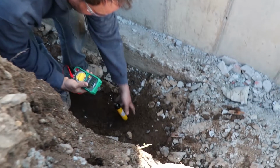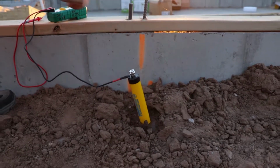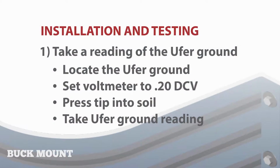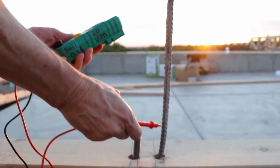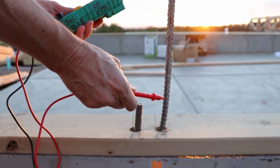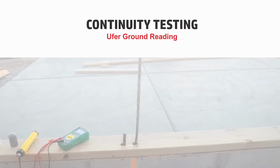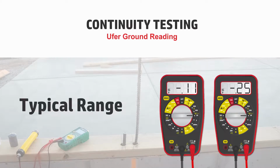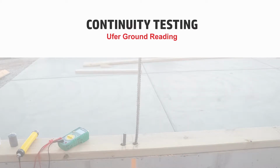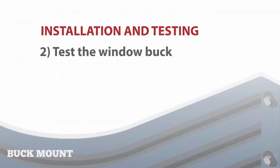Moist soil will give you the most accurate reading, so if the soil is dry, don't hesitate to add some water. Take a voltmeter reading from the UFR ground and write down the readings. This becomes part of the baseline for the rest of the testing. A typical UFR ground reading will be between -0.11 and -0.25. For the home shown in this video, the UFR ground read -0.18. This is normal.